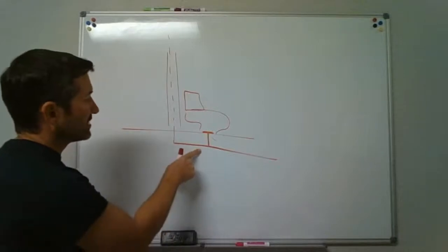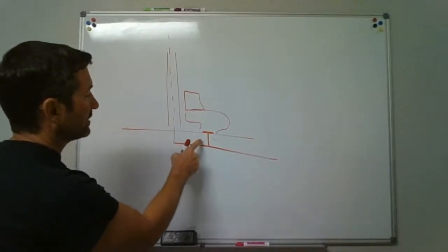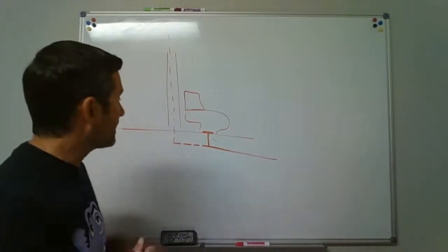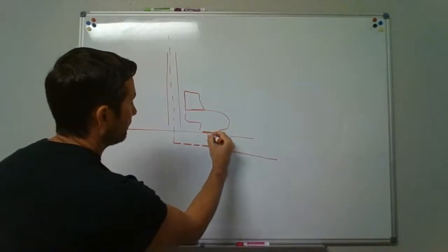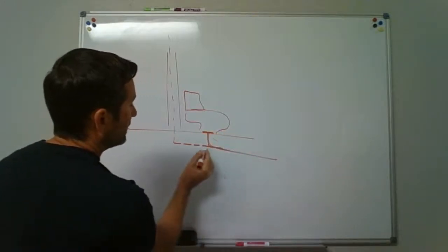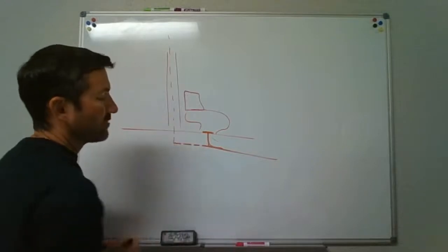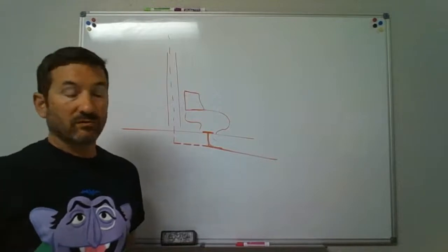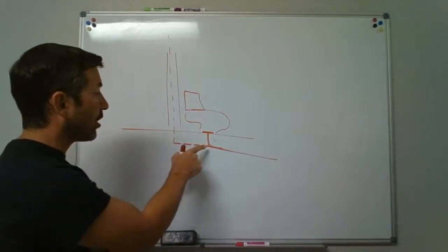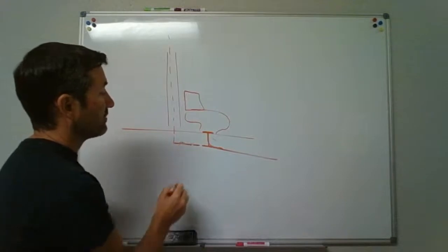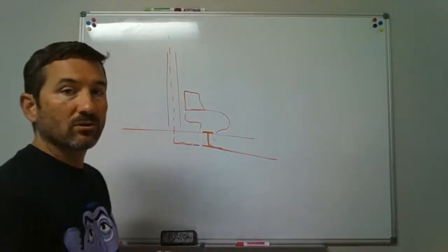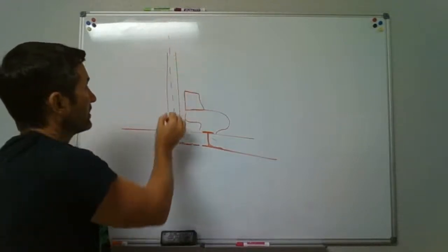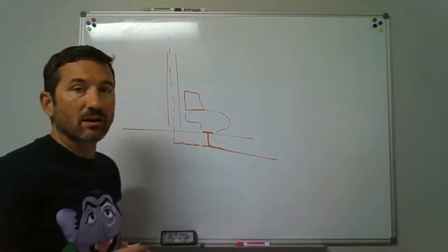This one, I really should dash, because if there's nothing draining down it, that is dry. When you flush this toilet, it's going to flush this way and go down. It's sucking air out of the back of that. And you know what? That's going to work just fine for however long it is until we get something clogged. And if we clog this vent somehow, we don't have a way of unclogging it. I guess you'd have to climb up on the roof and run your sewer machine, your snake, down through the vent from up top to try to unclog that.